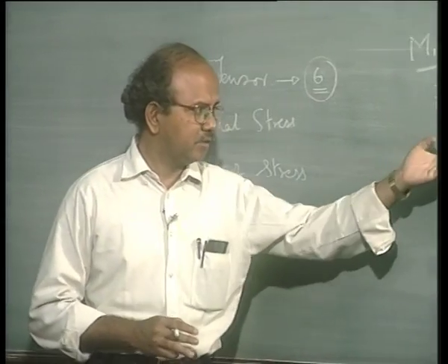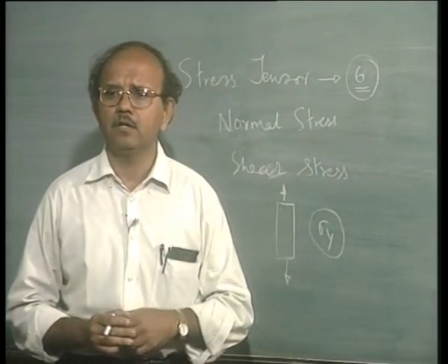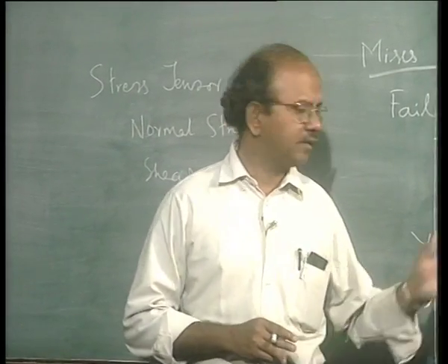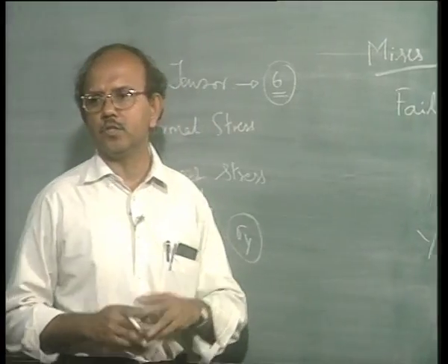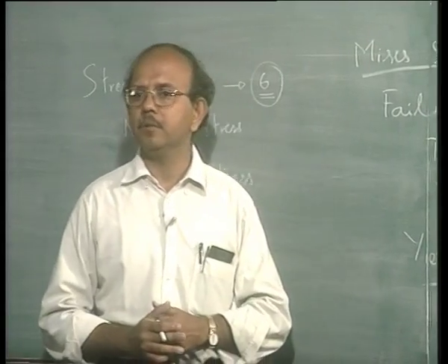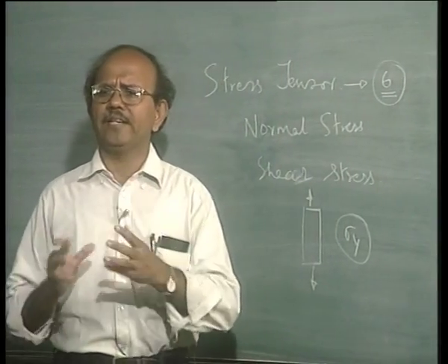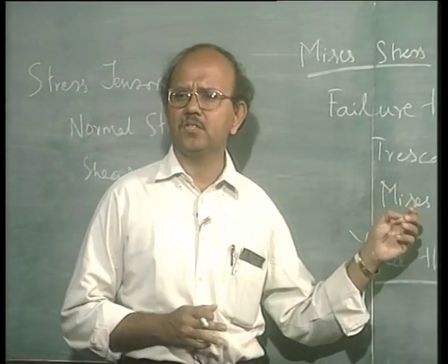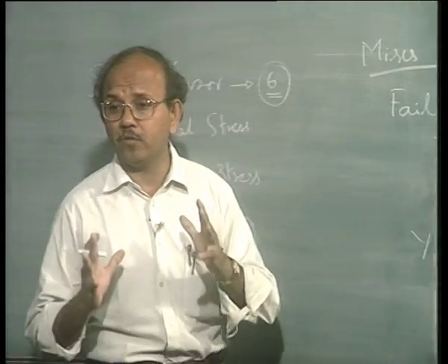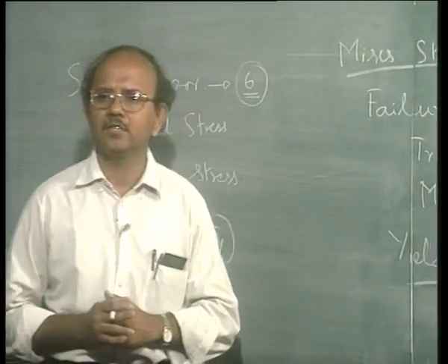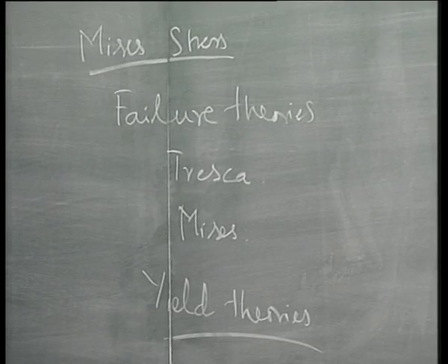Now, in order to go into the details of this, we need two things. One is, in order to explain Tresca, we have to define principal stress, and the other is to decompose the stress tensor in order to arrive at the theory due to Mises. In most finite element packages, people look at what are called Mises stresses, and hence it is very important we understand the basis of defining Mises stresses and what exactly it means, or else we will not be able to interpret the results.